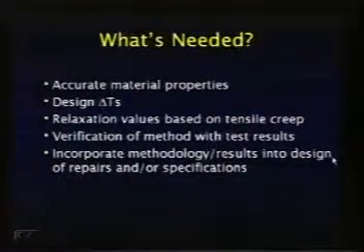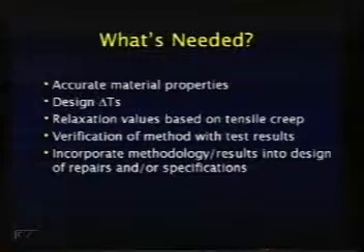What else is needed? Well, first of all, we need some very accurate material properties in order to use this method. We also need to have a better idea of what the design changes in temperature should be. That's very critical to making the calculation. We need to have a better idea of what that relaxation is for these materials. We found that one curve for epoxies, but for other materials, I'm not really sure what we should be using.